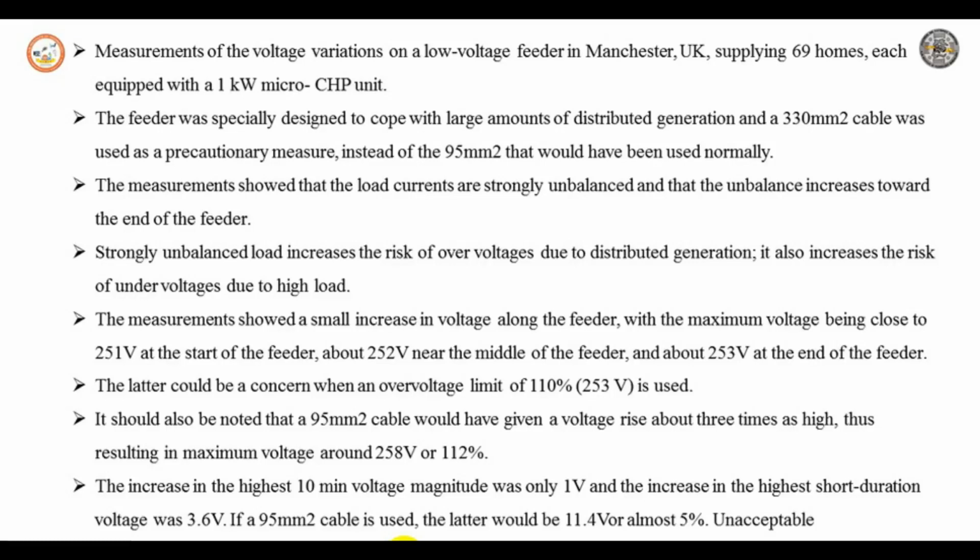Here the minimum load of only 0.1 kilowatt per customer was assumed, which is not a realistic value. Mainly this type of supply is usually for lighting the houses. They also considered micro CHP added to the network, where the maximum production is 1.2 kilowatts, at a power factor of 0.98. Here also the power factor is not accurate; they have assumed the power factor to be 0.98.